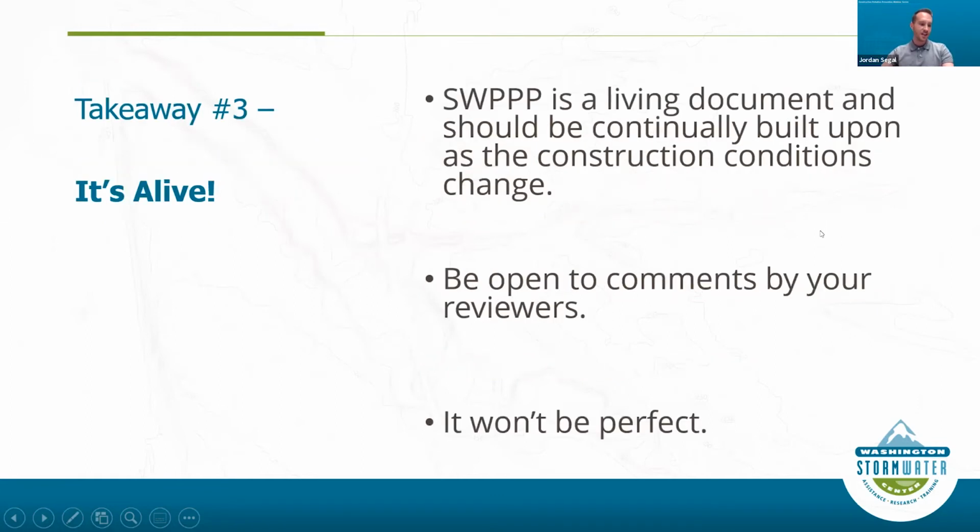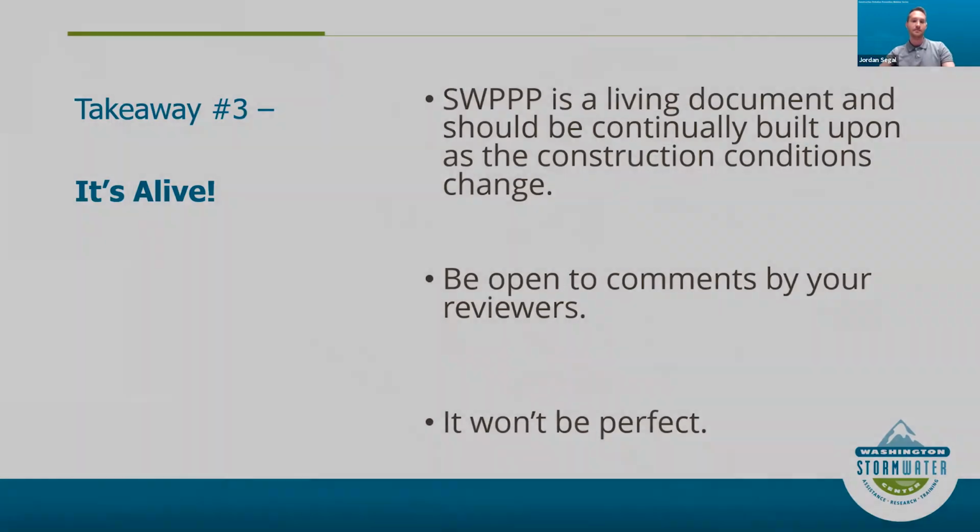And finally, understanding that your SWPPP is alive. Usually as a designer, you kind of complete that first one, and after your permit's approved, you hand it in, but understand that you could either be brought back in. It might have a question from your contractor, or maybe in your jurisdiction, sometimes the contractor puts together the SWPPP, but if you as the designer understand that it could be adjusted, and maybe allow in your plan for that adjustment to occur. And that's where you would discuss alternative BMPs within that SWPPP template, that document.